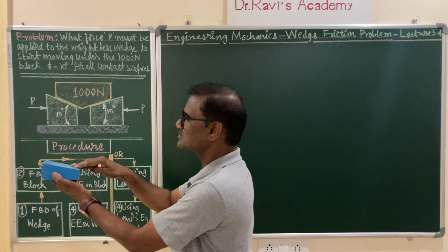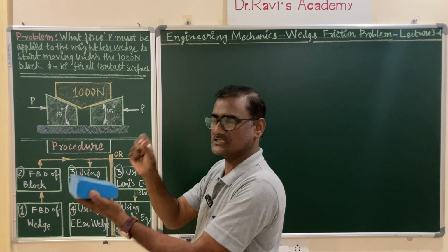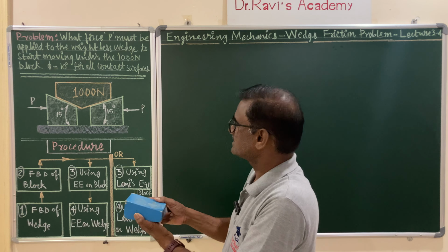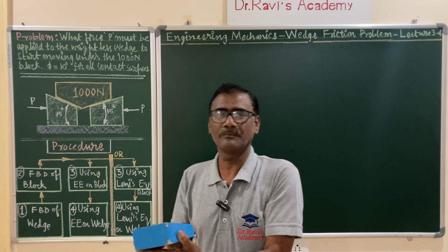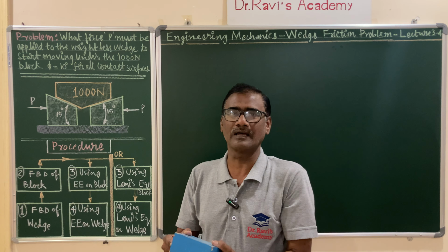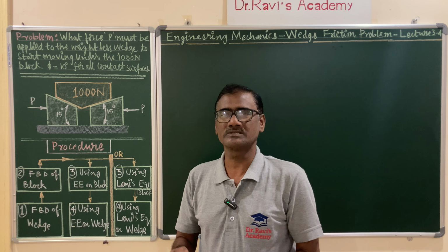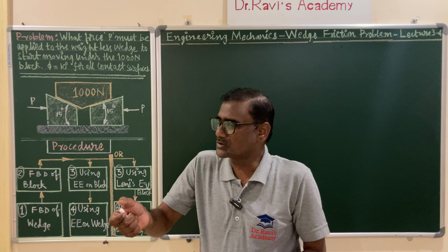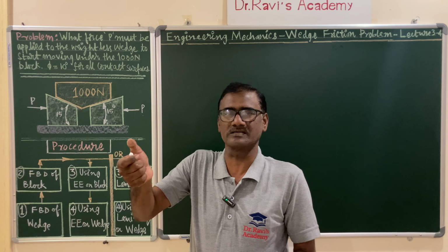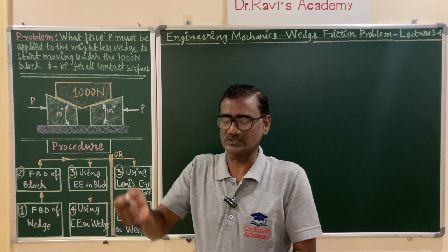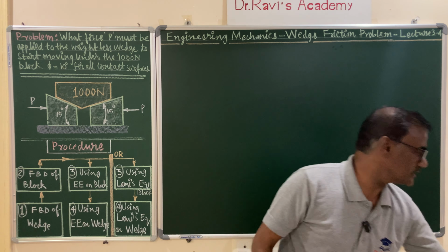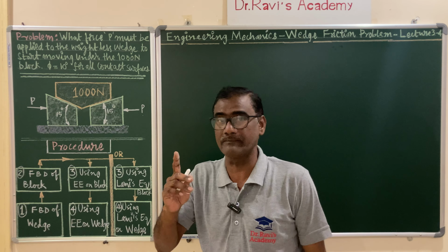The purpose of this small piece of material, especially in engineering applications, is for alignment of precast beams and maybe heavy machinery, where you want to lift very small vertical distances. In that case, you will go for wedges, which is not possible by any machinery.